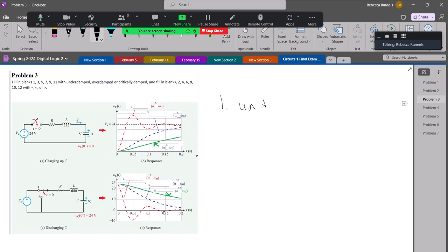Yeah, that one's underdamped. So any curve that is oscillating and going above and below the steady state is going to be underdamped. And then the one that reaches the steady state fastest, and so it doesn't mean it gets there fastest. I mean, the underdamped gets there fastest, but it's not stabilized yet. The blue dotted line has that nice smooth curve. That one is critically damped. And then the one that's kind of falling short of everything, that one is overdamped.